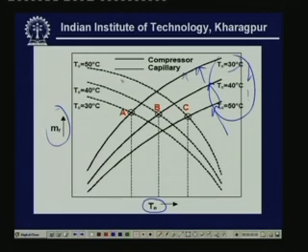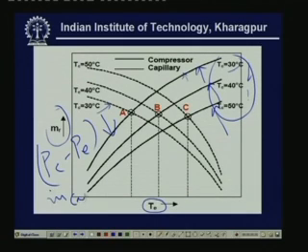And as I said, for the capillary the characteristics are entirely different. For example, for a capillary at a given condenser temperature, let us say 30 degrees centigrade, as the evaporator temperature increases, evaporator pressure increases. That means Pc minus Pe reduces, and as I have already explained, the mass flow rate through the capillary reduces. So that is what is shown here. For fixed condenser temperature, evaporator temperature is increasing and mass flow rate through the capillary is reducing. Similarly, at a given evaporator temperature, as the condensing temperature increases, condenser pressure increases, the pressure difference across the capillary increases, so mass flow rate increases.